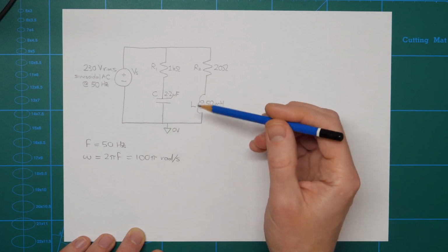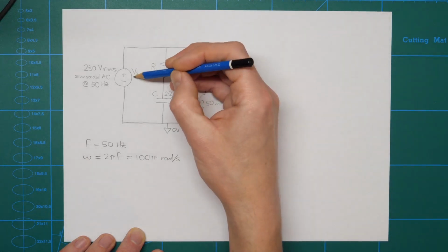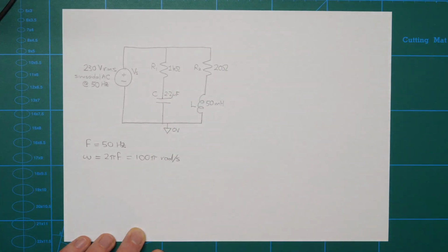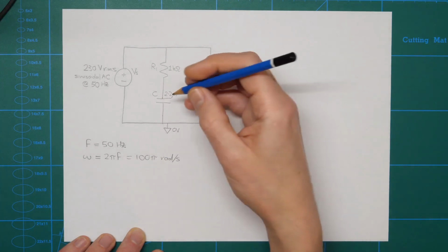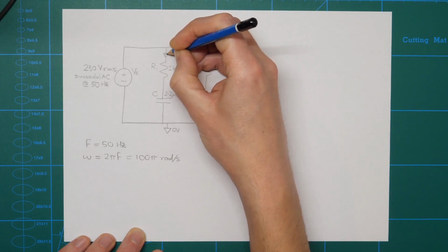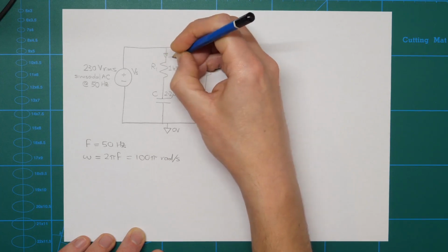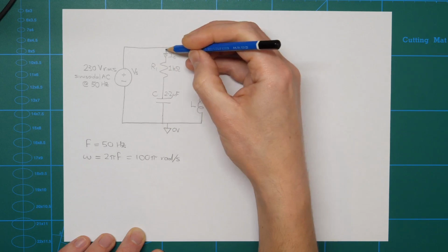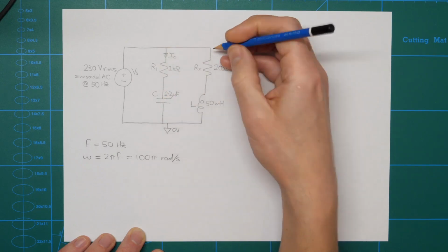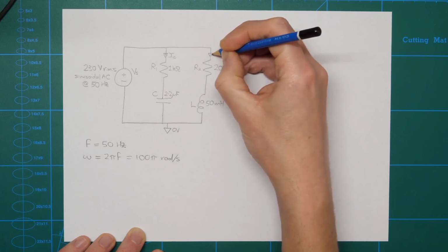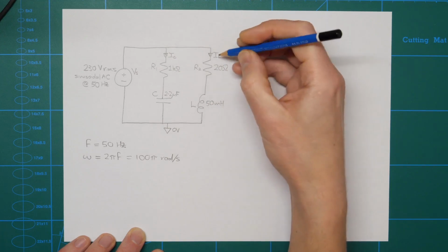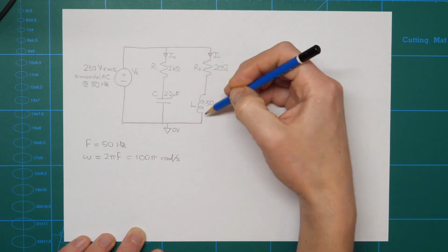Now before I go any further, I suppose I should say, what are we being asked to actually calculate here? VS, with an uppercase V, is the voltage phasor for the supply voltage. What I'm going to try and calculate in this example is the current in each of these branches as a phasor. I'll call this one IC, the current phasor that represents the current passing through the capacitor branch of the circuit. And then I'll have another phasor which I'll call IL. This is going to represent the current passing through the inductor branch of the circuit.